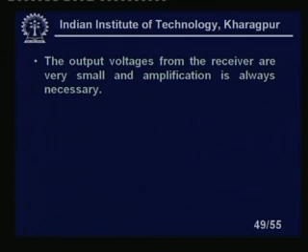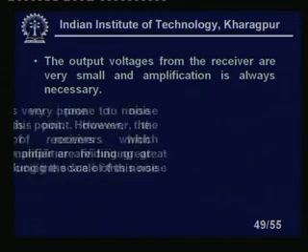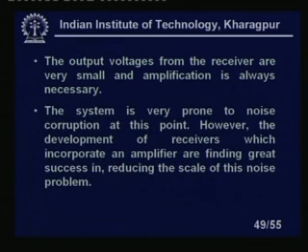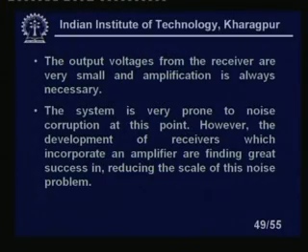The output voltage from the receivers is very small, and amplification is always necessary, as I told you. I can use a PIN diode, but then I need further amplification. That is the trade-off, because it has a larger bandwidth. The system is very prone to noise corruption.